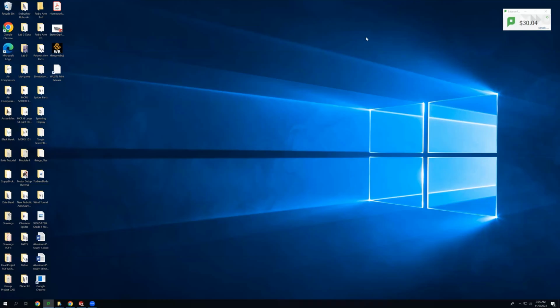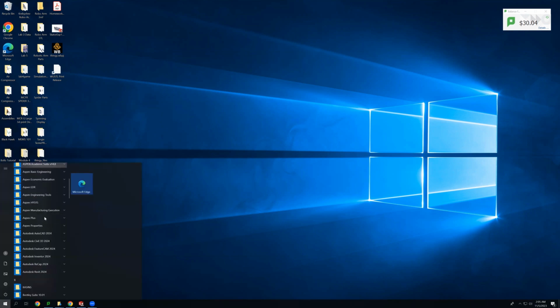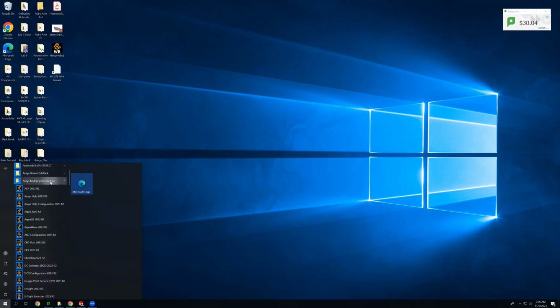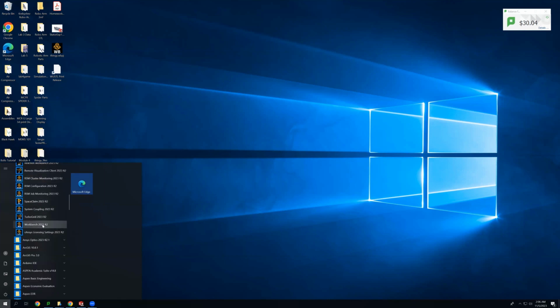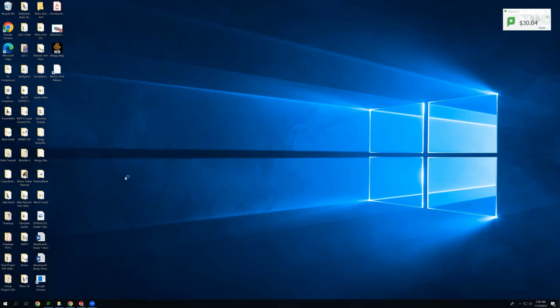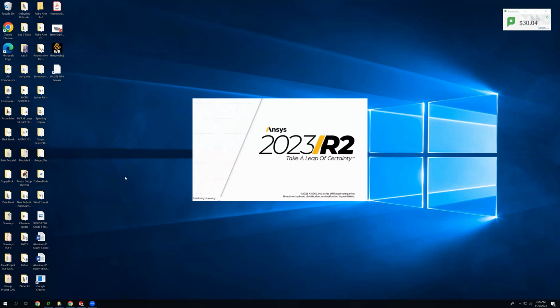Yes, so today we are going to be going over how to run an Ansys multi-physics simulation, a fluid simulation, on the Workbench. So first you want to go down to Start, then go to Ansys Multi-Physics 2023 R2, and then scroll down until you find Workbench 2023, and then click on that. And this is going to take about a minute to load.